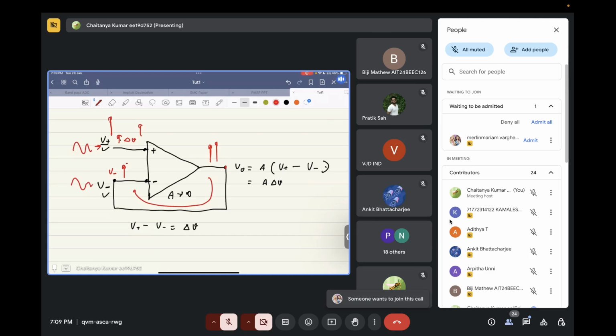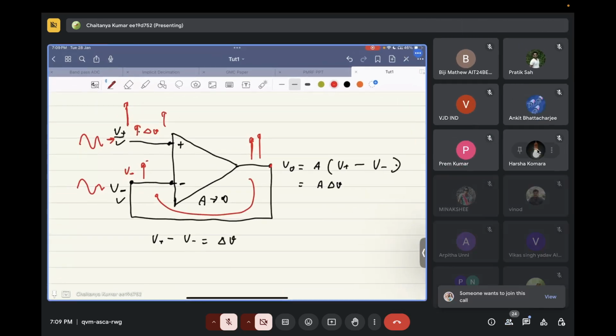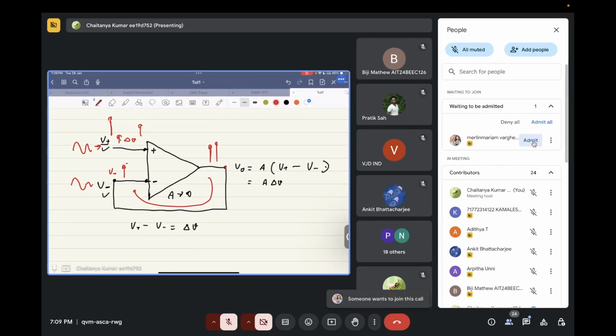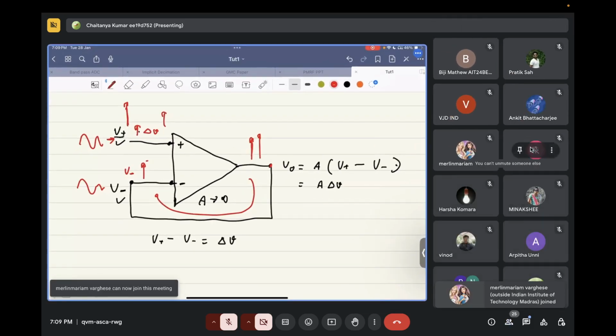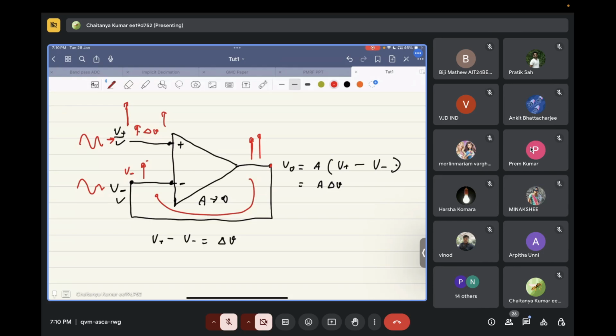And what is this concept called? When the op amp is in negative feedback configuration, the positive and negative terminals of the op amp track each other. What is this concept called? Buffers? No, no. The buffer is a voltage-controlled voltage source. Okay, virtual ground, correct. Virtual ground.